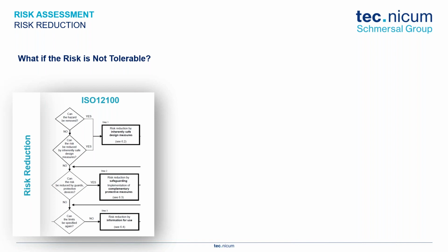Like, this machine's been on the floor for 5 years, 15 years, and we may not have enough justification to bring the machine offline to do a redesign. So on a new machine, more likely. Existing machines, less likely to do a redesign. What's more common on an existing machine would be adding some safeguards. So we can't do inherently safe design measures. Maybe we can implement some safeguarding measures, like some hard guards or some safety components.